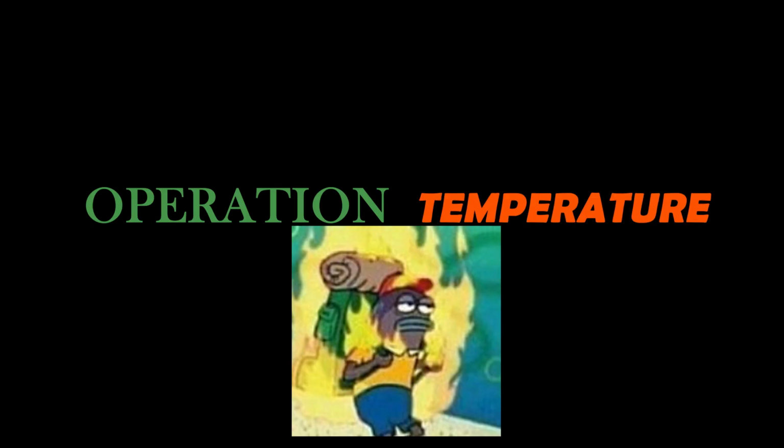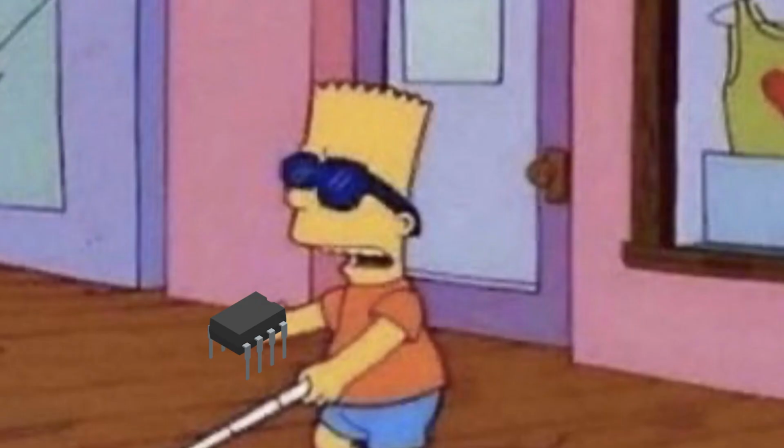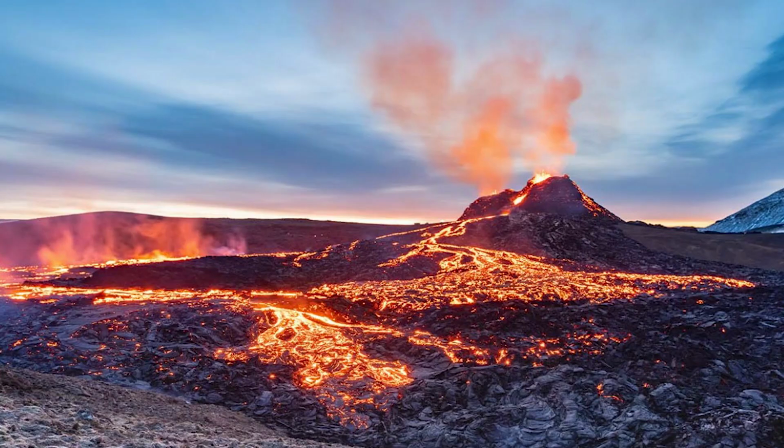We have operation temperature, which, as its name says, is just the temperature needed for the circuit to work normally. This is usually not so looked after since it's not common to work with an LM741 in an environment of more than 125 degrees Celsius without dying to overheating. However, what if I tell you this? Let's say that it is your job to make something as ridiculously hot as a volcano thermometer. That thing is absurdly hot. So I don't think you should use the LM741 for this application.